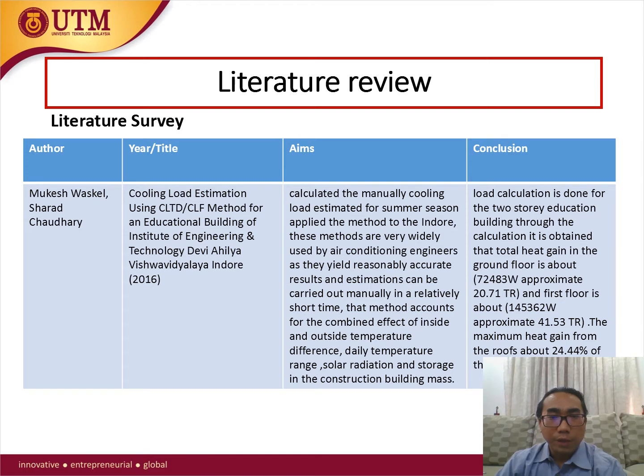These methods are very widely used by air conditioning engineers as they yield reasonably accurate results, and estimates can be carried out manually in a relatively short time. The method accounts for the combined effect of inside and outside temperature difference, daily temperature range, solar radiation, and storage in the construction building mass.